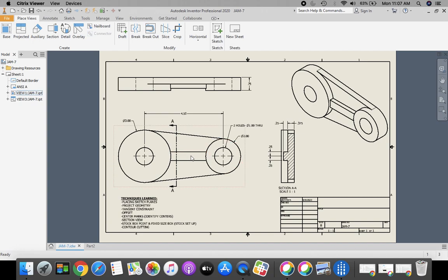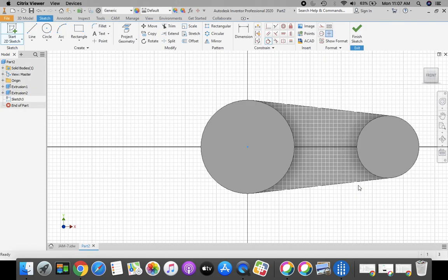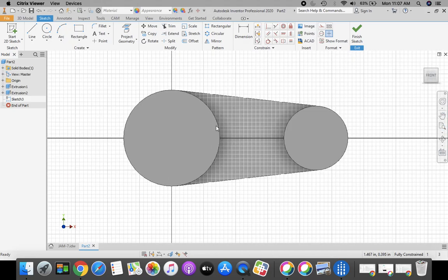Next, let's take a look at placing this strengthening piece. It's kind of like a rib down the middle. Let's take a look at doing that. We're going to once again 2D sketch. We're going to place this on the front of that little platform. Click front in your world view cube or magnifying glass piece of paper to zoom all. And we're going to create that with our line tool.